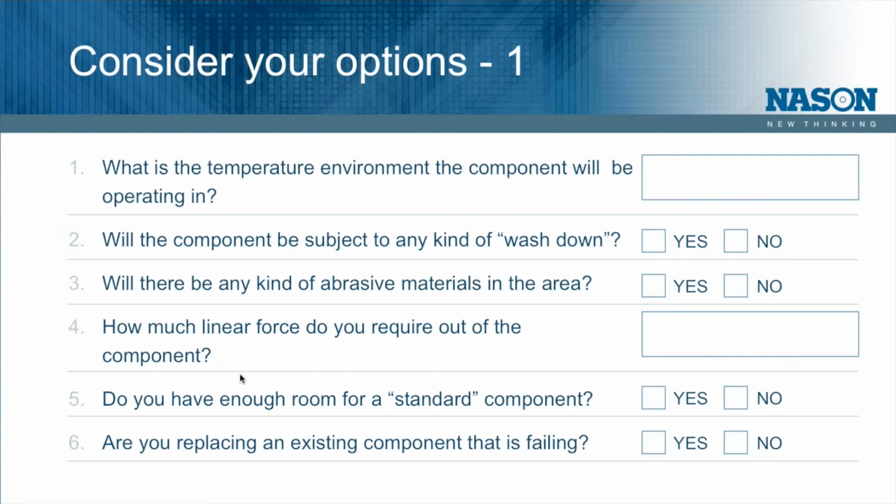What is the environment that the cylinder will be operating in? Is it high temp? Is it low temp? What's the environment like? Will the cylinder be subject to any type of washdown? Will there be any kind of abrasive material in the area, such as metal shavings, grinding dust, flour, anything that could harm the cylinder? How much linear force do you require out of the cylinder? Do you have enough room for a standard component?